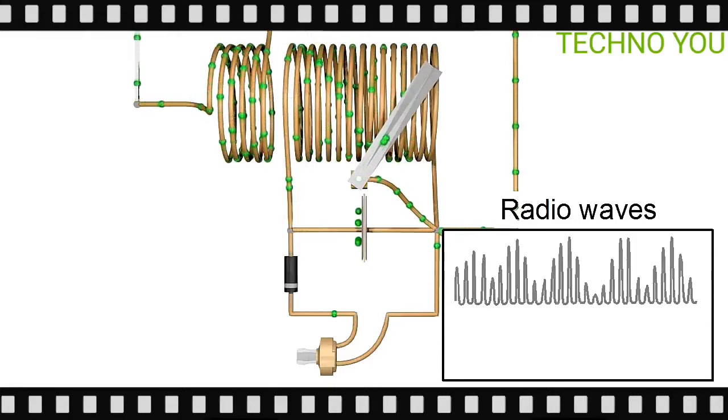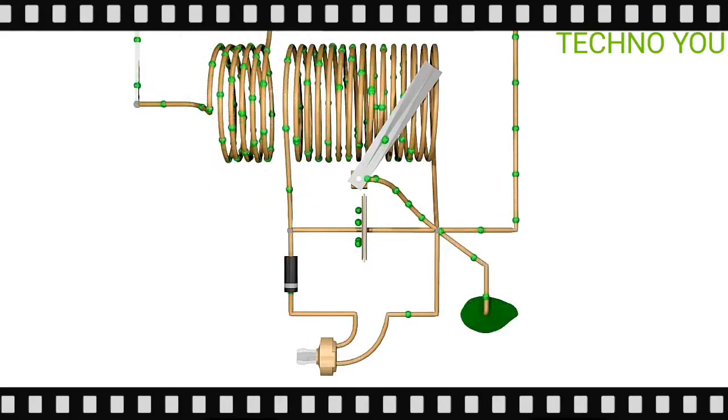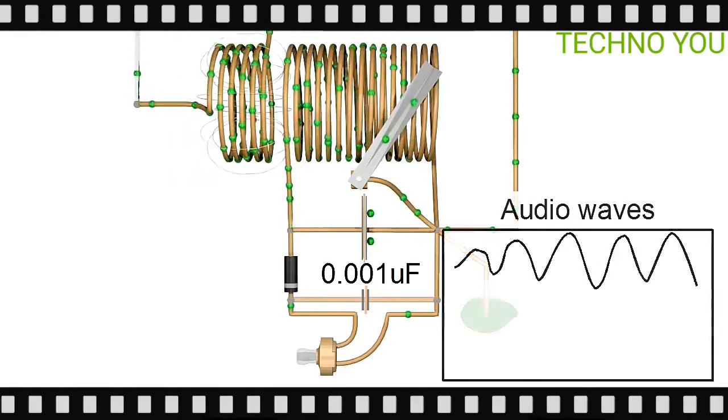In reality, the crystal is still seeing the radio wave, even though it's reacting to the waves only in bunches. So it's not quite as smooth as the original audio wave. An improvement you can do is to add a capacitor here that'll smooth out the radio wave, and then you'll be back to the original audio wave.